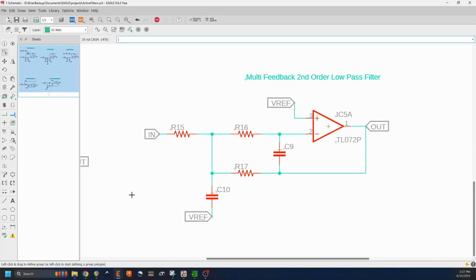If we were to replace 1 and 2 on this op amp with pin 16 and pin 15 of the PT2399, we would be able to see, oh yeah, that's exactly the arrangement that gets used on the input to almost every PT2399 circuit.